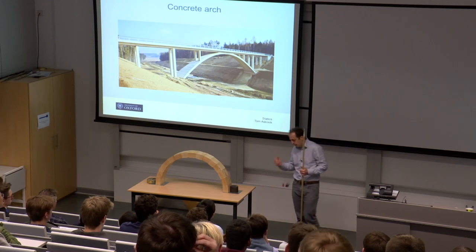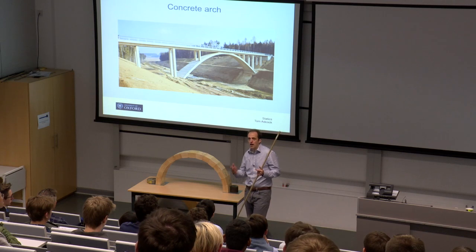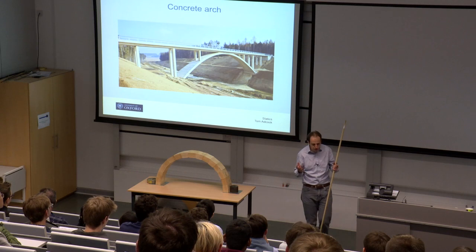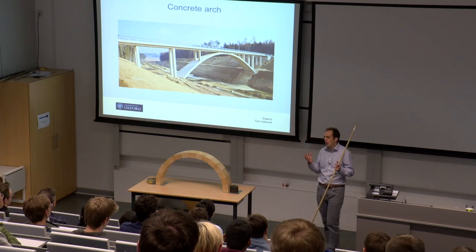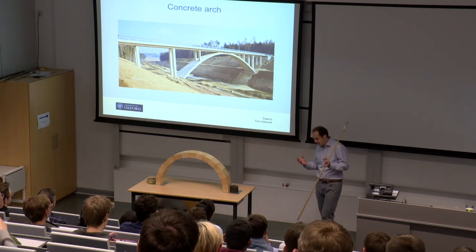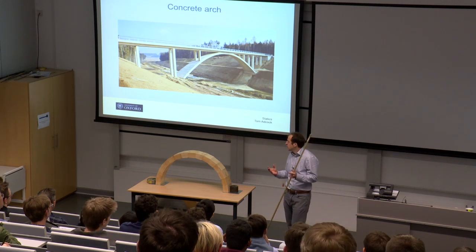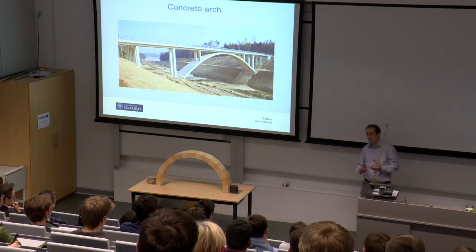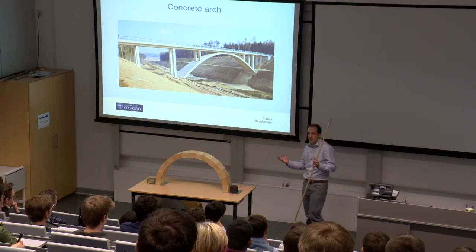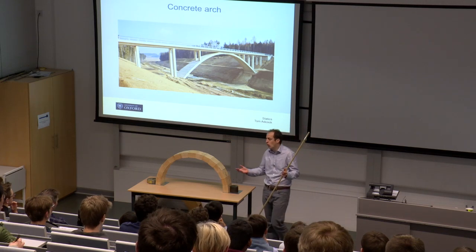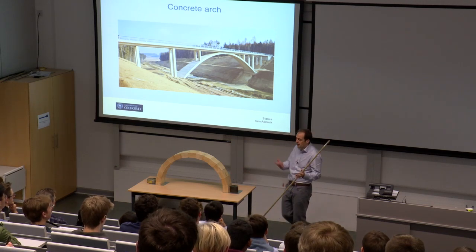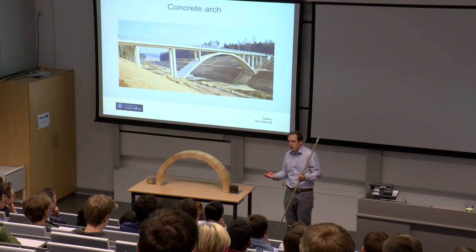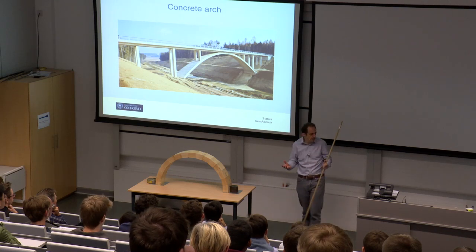So let's just think for a minute why people design things in arches. Well, essentially, it's quite an efficient way of carrying a load, and that's particularly true for certain materials. So here we've got a concrete arch, and typically around Oxford you tend to get brick arches or stone arches, because that's the standard building material of most Oxford colleges. So why is an arch a good way of carrying that load?